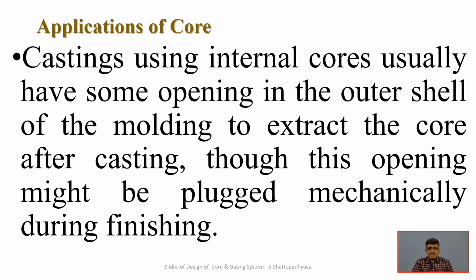So the castings using internal cores usually have some opening. Why an opening? Because the core sand has to be collapsed after the casting, and the outer shell of the molding has to be opened to extract this sacrificial core after the casting through this opening, which is plugged mechanically during the finishing.